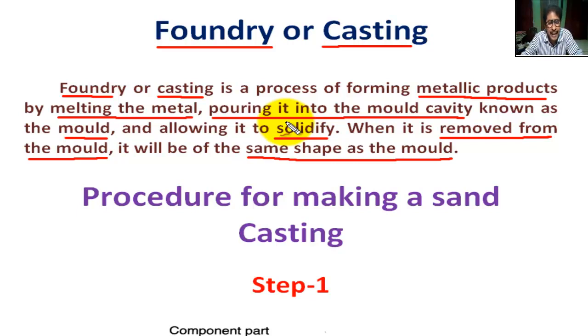Next, pour molten metal into the mold cavity. Next, allow it to solidify. Next, remove it from the mold cavity.